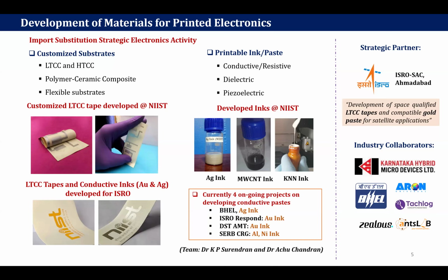In customized substrate, we are basically into LTCC and HTCC substrate. So what is LTCC? LTCC is nothing but low temperature co-fired ceramic technology. You might have seen the MEMS technology. Some of you might be familiar with the word MEMS, micro electromechanical systems, whatever devices you are making on silicon substrate. That kind of technology, especially at micro scale and meso scale, is called MEMS, with the mechanical and electronic parts and actuation and all those things.